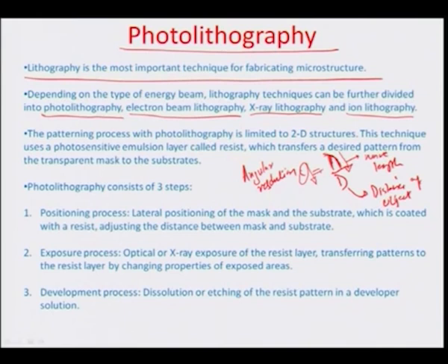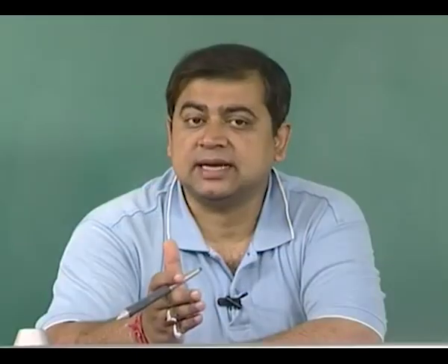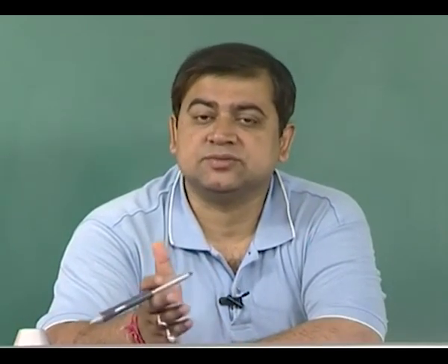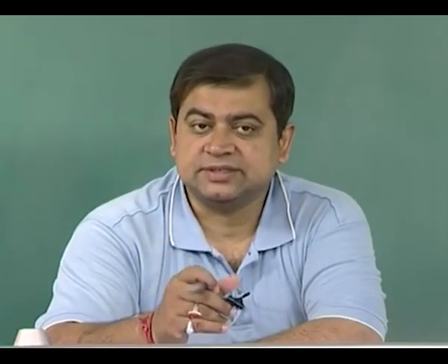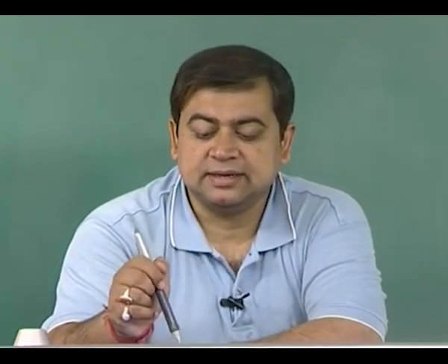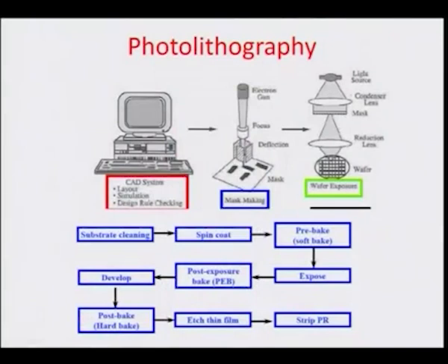And then, of course, there is the third step, development, where, just as in photography, whatever has been imprinted onto the top of the resist from the mask can be removed by physically developing it in an etching solution, and whatever parts are exposed are either removed or they stay, thereby formulating micro-size features or vias, whatever is needed.